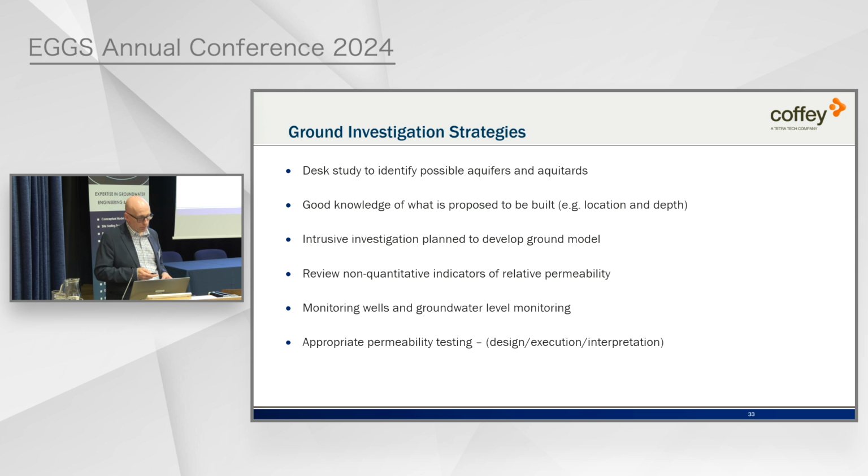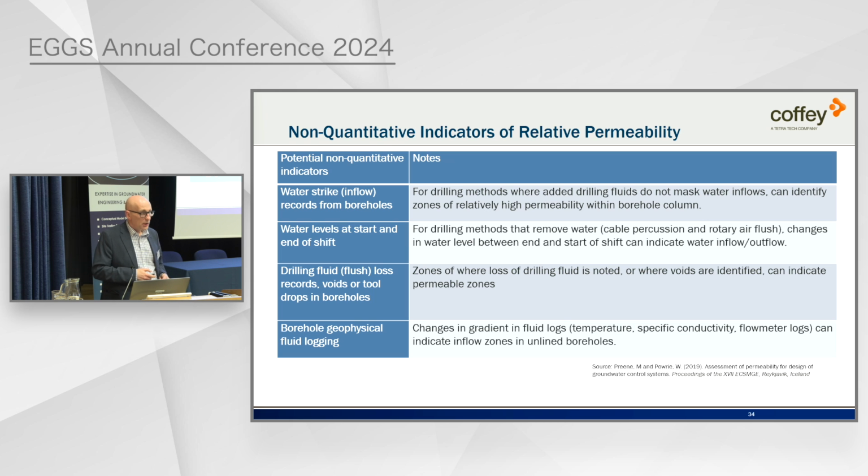And finally, you need to have appropriate permeability testing. And I'll go through these in a little bit more detail. So I'm a big believer that when you look at both the final borehole logs at the end, but also sometimes at the field logs that come from the drilling crews, there could be a lot of information on there that sometimes we don't fully value.